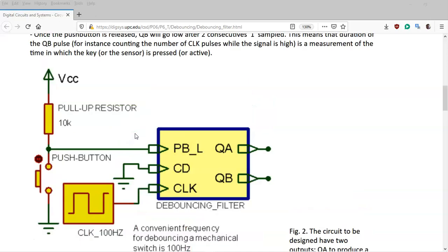So the debouncing filter is specifically this thing, okay? A kind of digital system that is like a D flip-flop, but with something else, so that you can generate the perfect pulse that you like, whether a single clock pulse or one for the full duration of the event, because some applications need one and other applications another. So that's the typical debouncing filter, a digital debouncing filter, specifically a finite state machine, right?